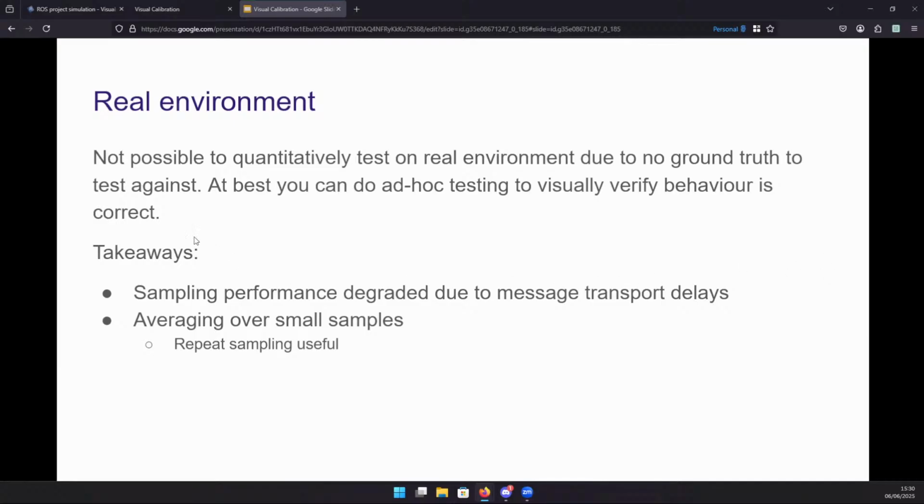So when you saw how sluggish it looked, it's not because the package is straining the system computationally. I had run it previously with HTOP, and neither memory nor CPU was really being pushed. It's very much the underlying message transport system that ROS2 is using, the middleware, suffering in the real lab environment.